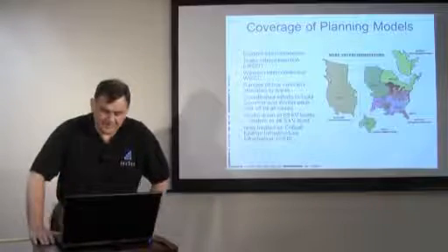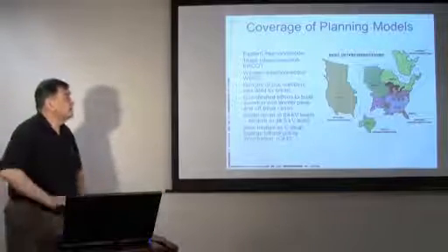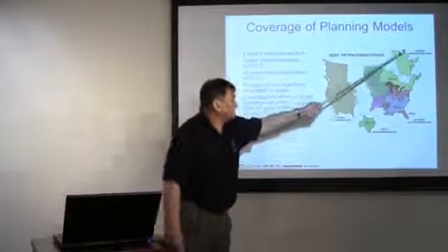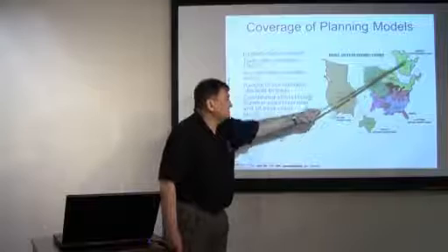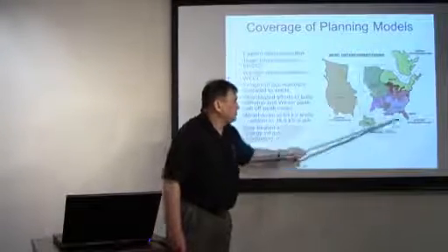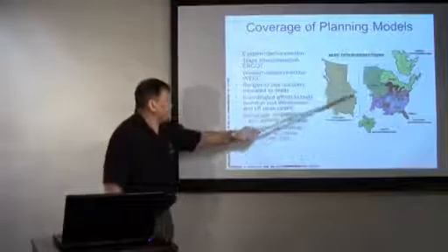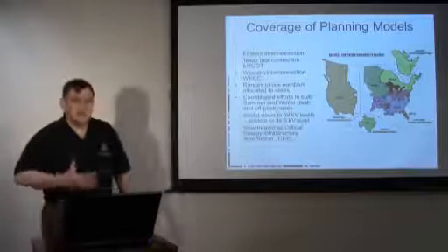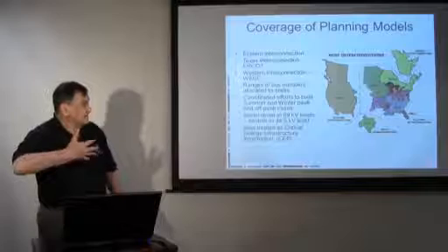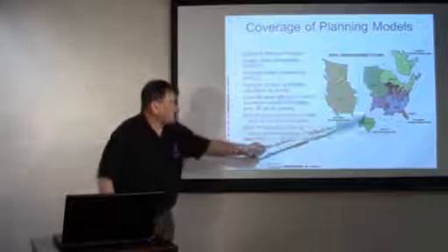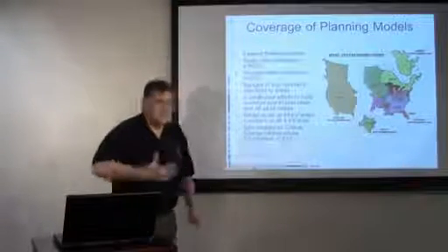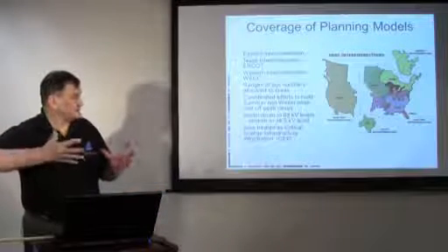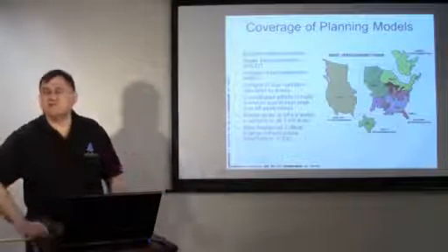But for planning, basically, we've got these modeling groups. One for the eastern interconnection, including all of Quebec, even though they are actually connected through DC lines and are synchronous. This whole group works together. We have WECC, which also has a modeling group, and then we have Texas. And because these are asynchronous interconnections with DC lines, the studies can be isolated from each other from a stability point of view.